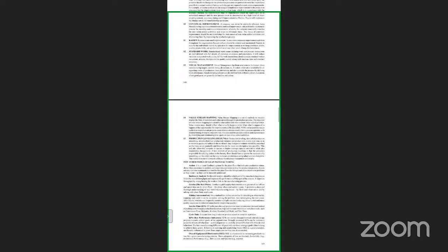And standardized work means defining the work and process instructions, which will help with the details of operations or processes and parameters, which in turn will reduce the work cycle. All work instructions should contain standard worker movement, actions, checkpoints for quality and safety, along with machine time and standard inventory.